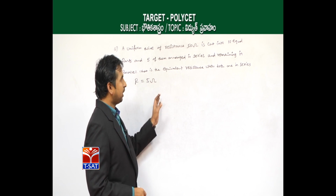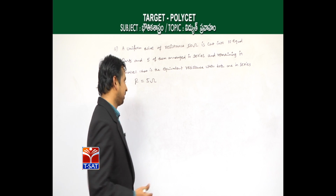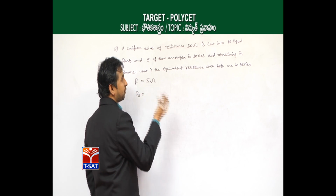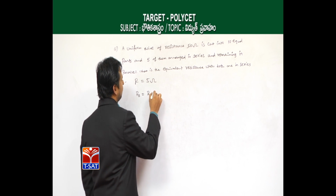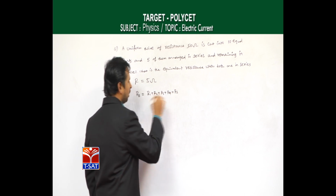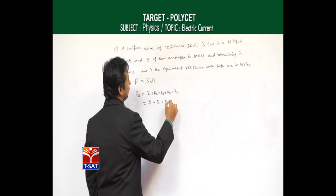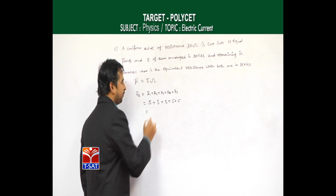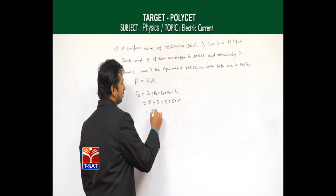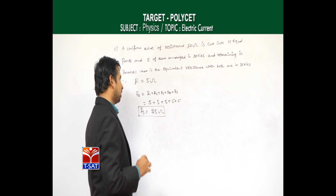Each one of these 5 ohm pieces is first arranged in series, and later arranged in parallel. For the series connection, with 5 resistances, we have R1 plus R2 plus R3 plus R4 plus R5. In all 5 cases we have the same resistance of 5, so 5 plus 5 plus 5 plus 5 plus 5, which totals 25 ohms. This is when arranging them in series.